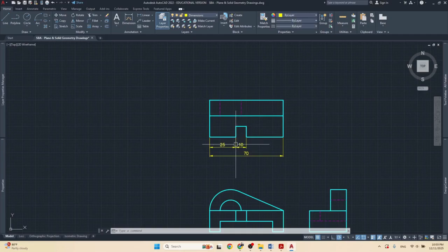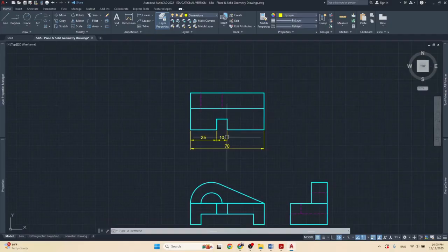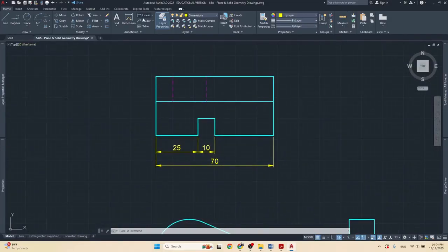And here's another rule: in technical drawing, in this kind of drawing, we do not repeat ourselves, okay, because it makes the drawing messy. So if I have 70 millimeters here, I don't need to put 70 millimeters up here again. Why? Because obviously if it's already here, I don't need it up here. So you could even remove this one and leave it like this. You show that, and you have the overall above, and then the person would know automatically that this is 35 because I minus this from that.